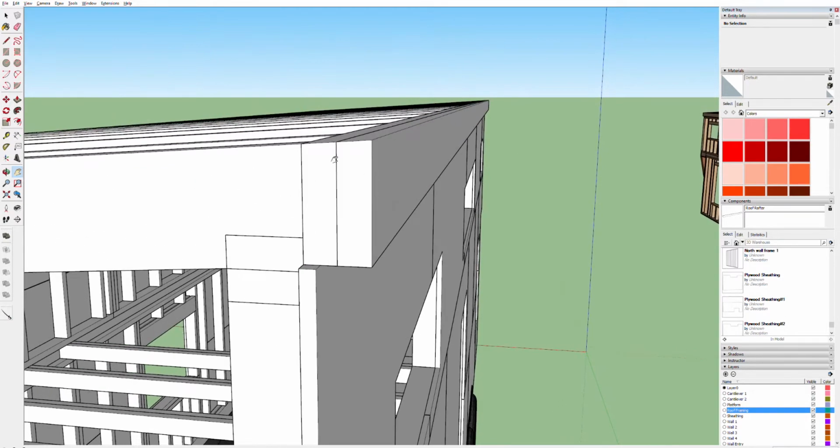So what's going to happen on the roofing, on the top of the peak of the roof, we're going to have our sheathing on the whole roof, and then we're going to have our water barrier, and the water barrier is going to come up and over and on the outside of this packed out 2x4s and stapled down probably right there, maybe even underneath this a little bit.